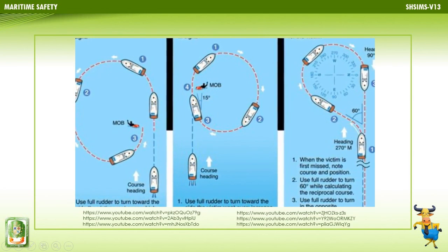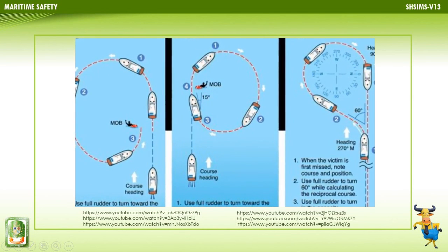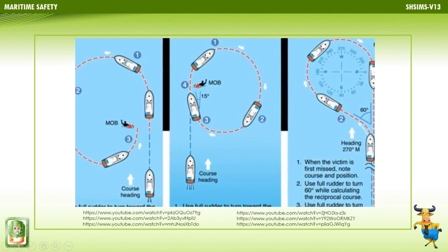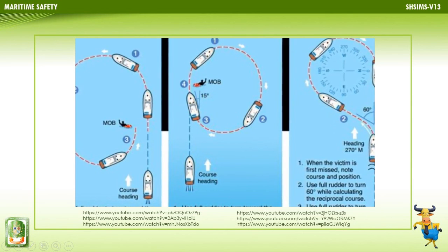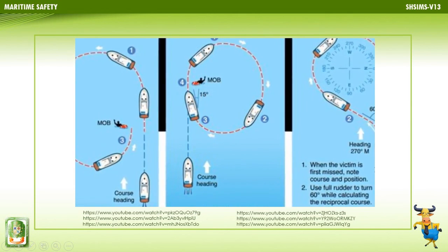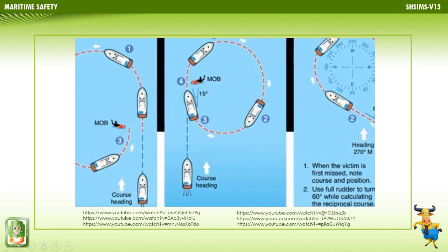The need to keep a visual reference on the floating datum or wake means that this method needs a relatively small turning circle to be effective. Unlike the previous 2 methods, the first step is to slow down to a near or full stop, then turn short around. Motor ahead on the reciprocal course.